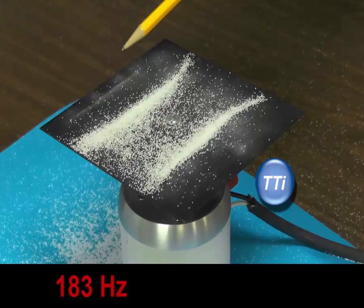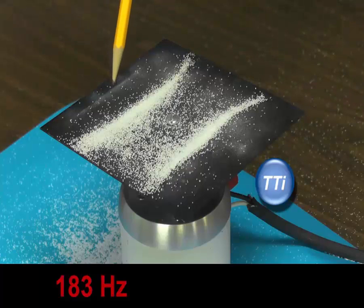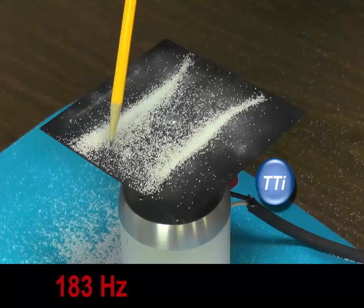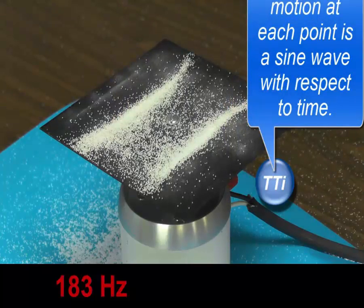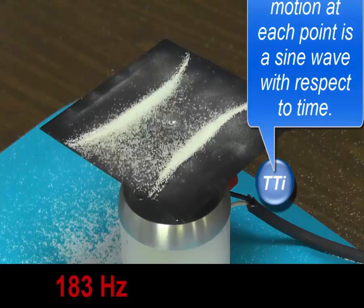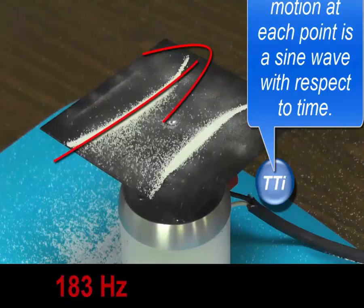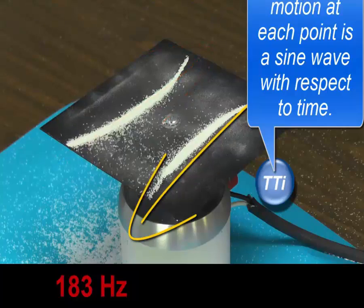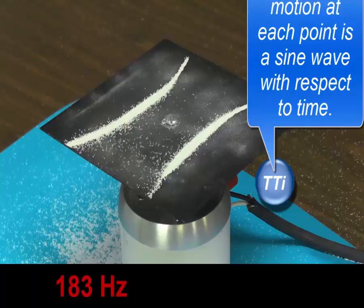Remember that every time we cross a node line, we change phase, and so if this part of the structure is going up, all of this central part is going down, and all of this part is coming up as it goes through the sine wave. There we see. They're not perfect straight lines, slight curves to them, but they are acting more like a beam than a plate. Let's see if we can find another resonance.